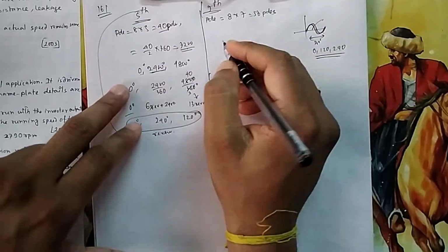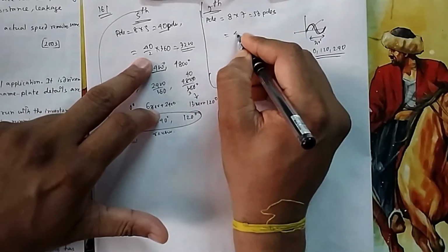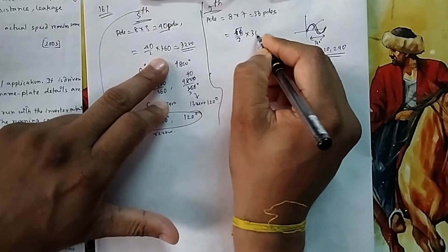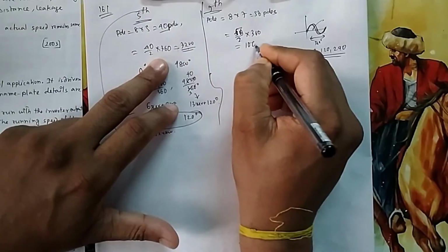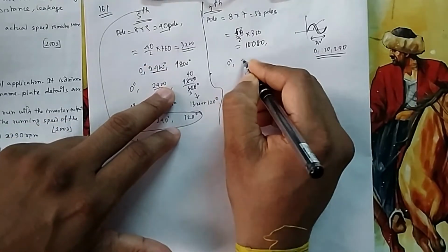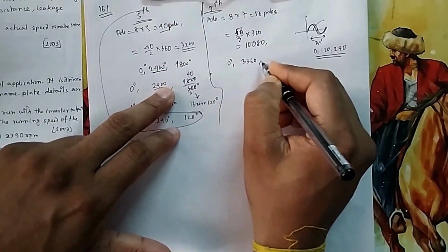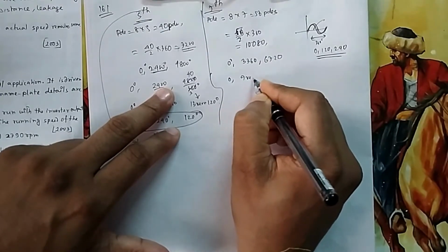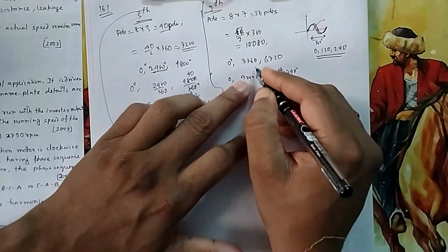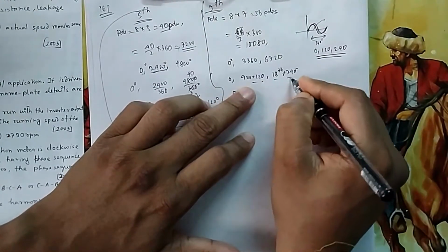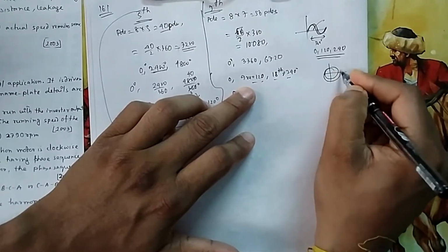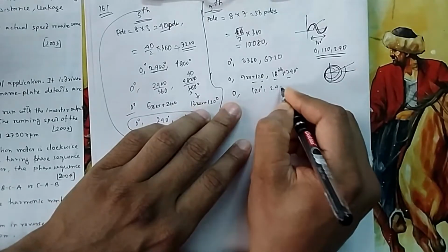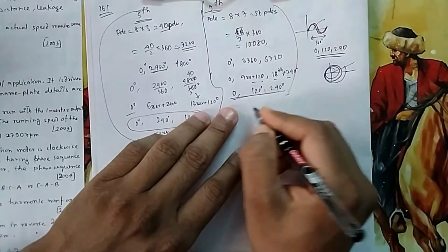What will the 7th harmonic do? Similarly, you can calculate the total angle for one revolution. It will be 56 by 2 into 360, which gives 10080. So the first one starts from 0, the second from 3360, and the third from 6720. Divide by 360 and you will see it is 9 revolutions plus 120, and 18 revolutions plus 240. So it finally comes at 120. It will look like 0, 120 and 240, so it is the original sequence. So it will move in the forward direction.